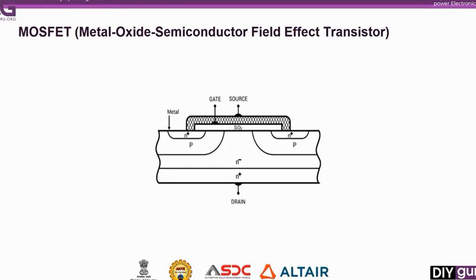When a positive gate voltage is applied with respect to the source, the N-type channel is formed between source to drain. Now this is shown in the figure: there is a parasitic NPN BJT between source and drain. Now to avoid this BJT turn on, the P-type body region is shorted to the source region by overlapping the source metallization on the P-type body of the MOSFET. The result is that a parasitic diode is formed between the source and drain terminals. This integral diode plays an important role in half and full bridge converter circuits.